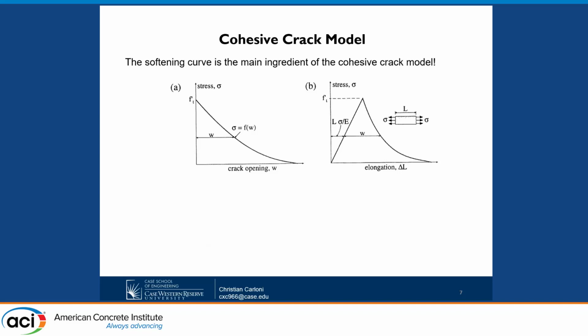And by the way, materials like fiber reinforced concrete still behave the same way. And initially they behave exactly with the same softening curve. Then they have this long tail because the fibers, of course, will restrain that opening and they let you open more and more.